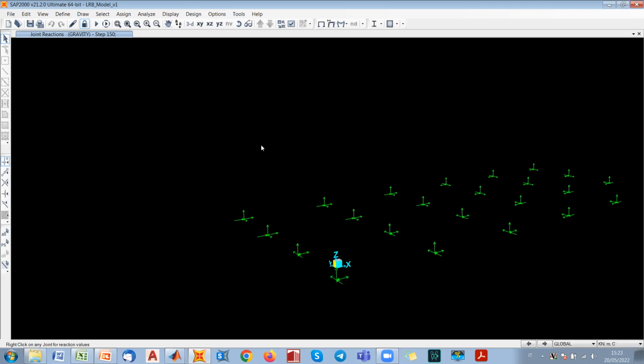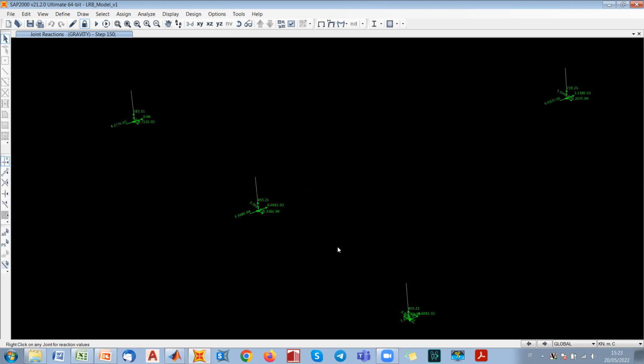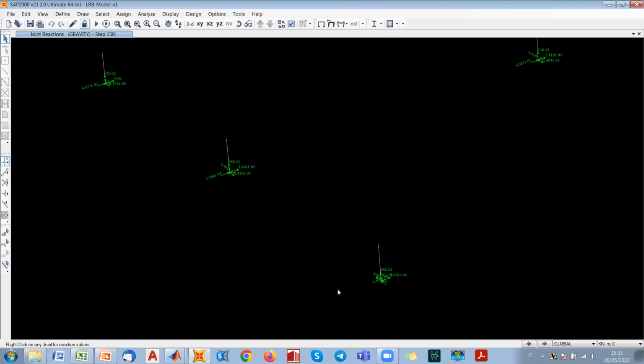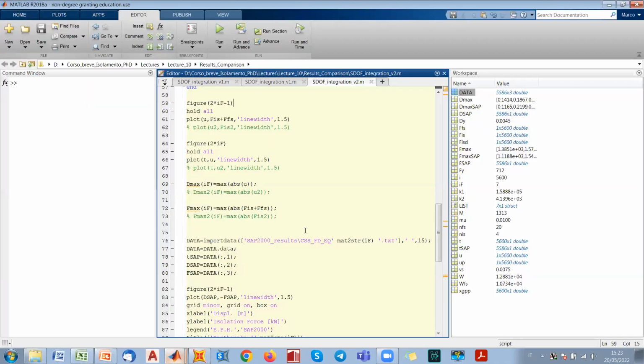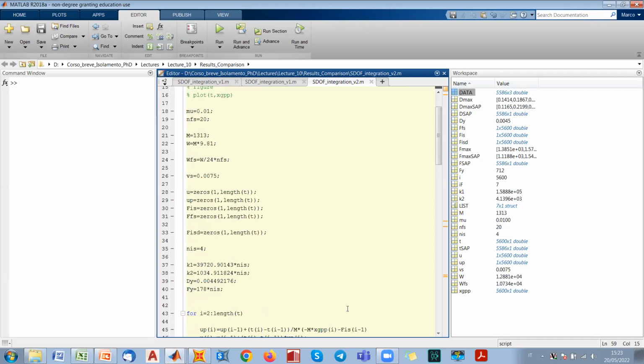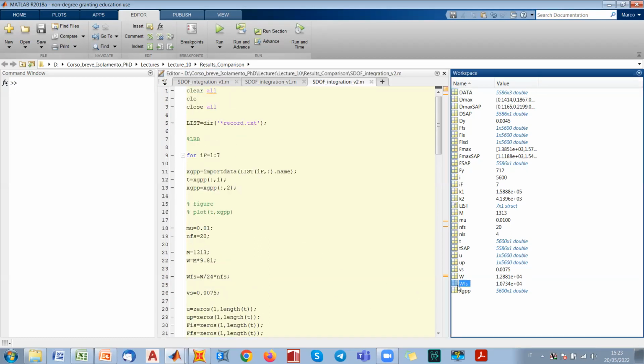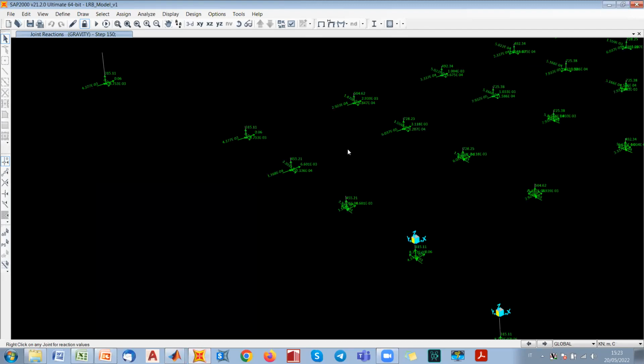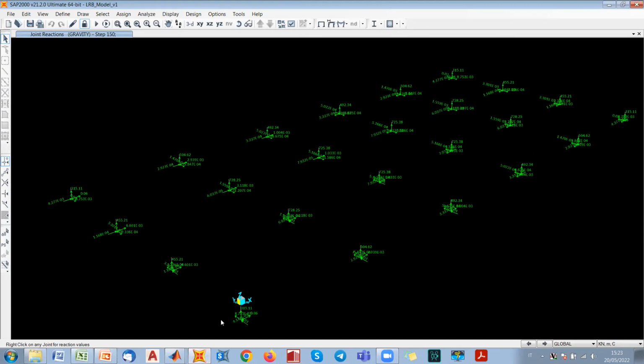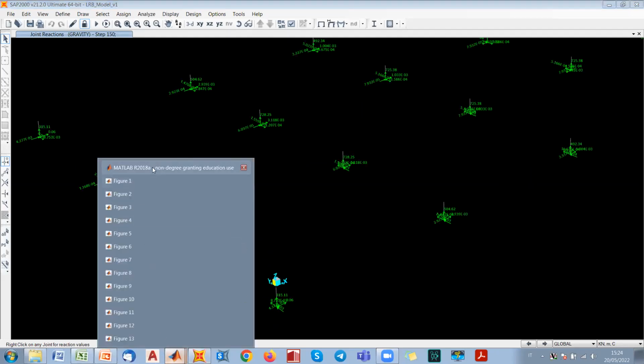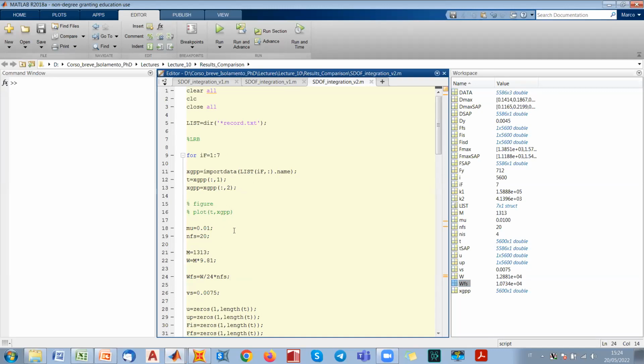So you see that here we have 455, and actually for the single degree of freedom, we considered this summation, which is something like 10,000 kilonewtons. That should be a little bit higher, because we have the total weight minus the 4 reactions applied to the devices at the corners, the 315. So we can try this just to check if we can get some better results.